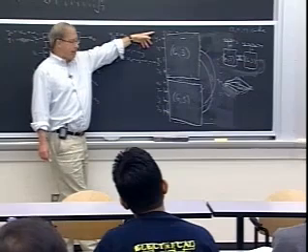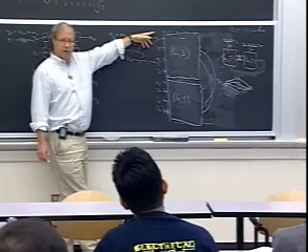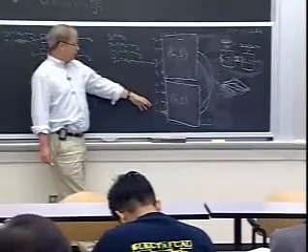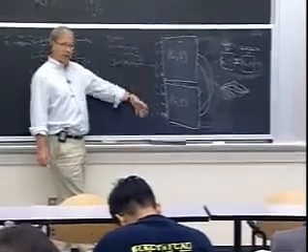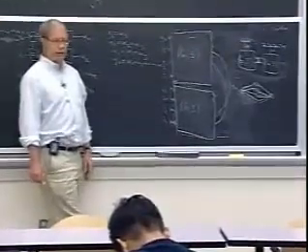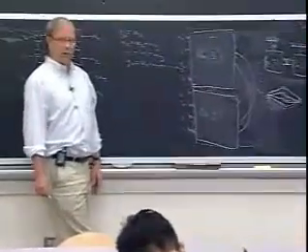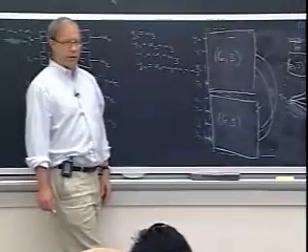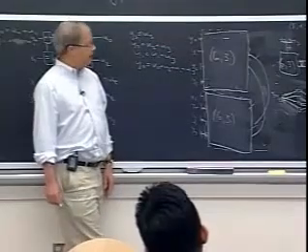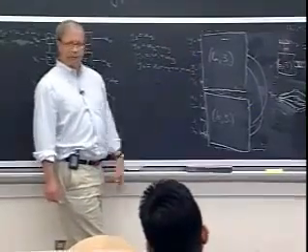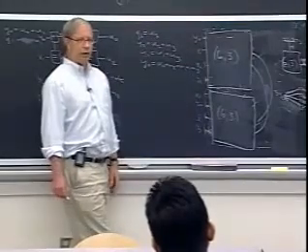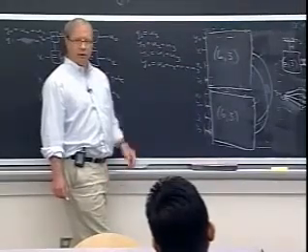All right. Now that isn't actually what we've been doing in the Viterbi algorithm, for instance, or in general in our decoding. We've said we want to minimize the probability of decoding any code word on a sequence basis. We want to minimize the probability of error in decoding the whole sequence. So these are not exactly the same thing. In fact, if you do max APP decoding, you may not even get a code word. You'll make individual decisions on each of these bits, and that may not actually be a code word. There's nothing that requires it to be.